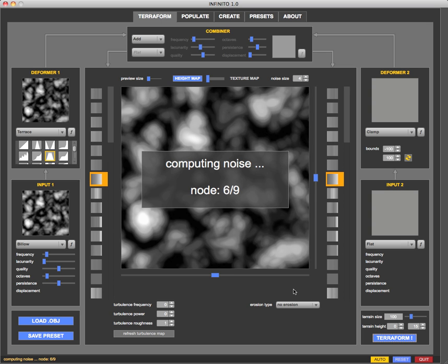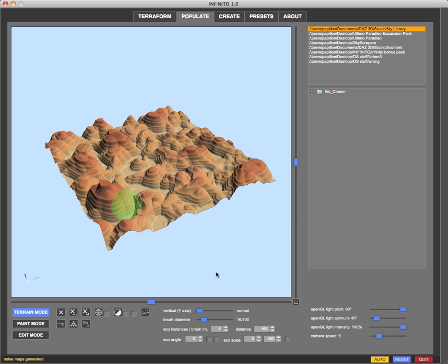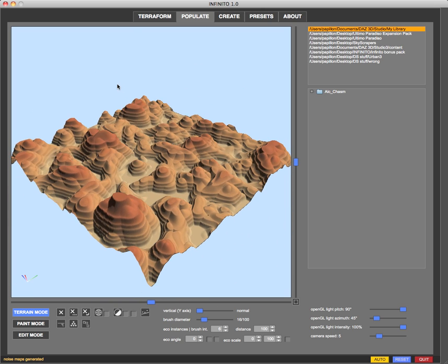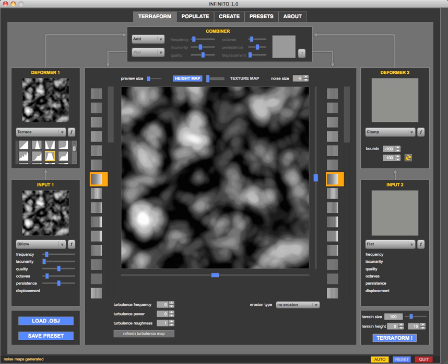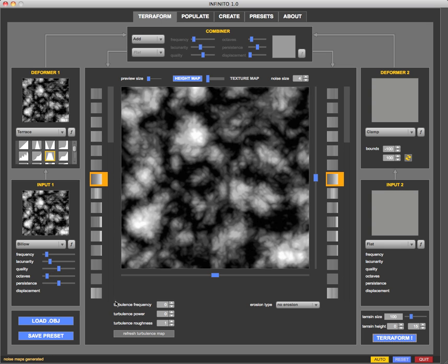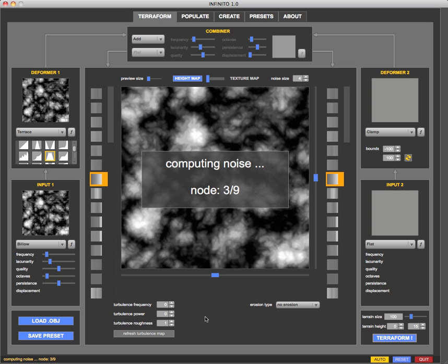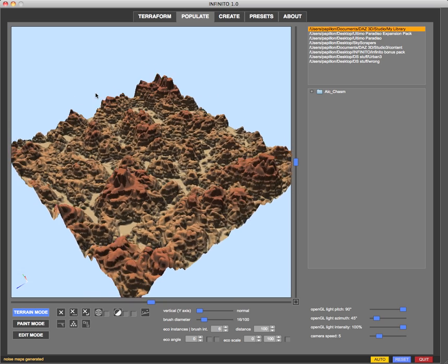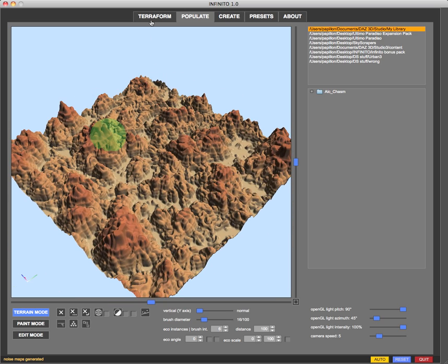You see now that our terrain has a very smooth look, and well, this is because we didn't apply any turbulence effect yet, and also because we are very low on linearity and persistence. We might perhaps also use some more persistence to get more interesting results. But this will come later, and when we explore the turbulence section, you will see how things will get even more interesting.